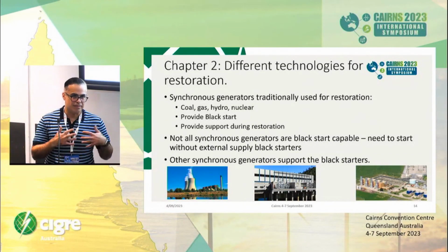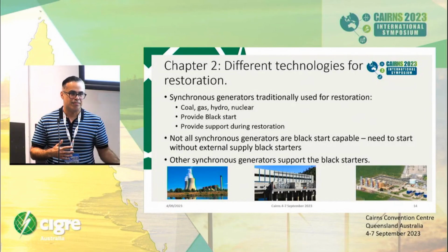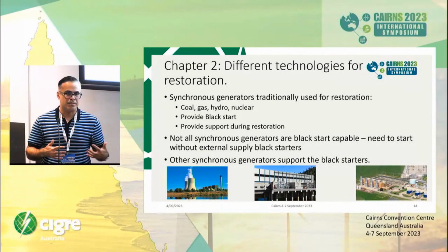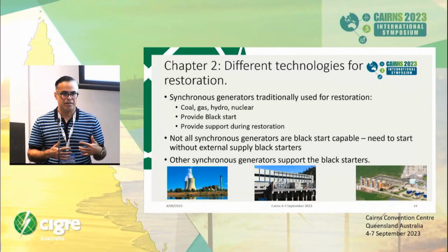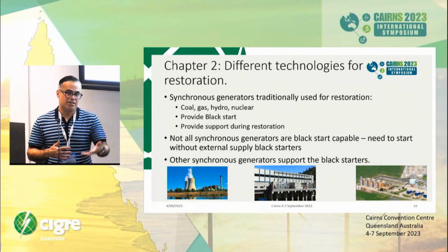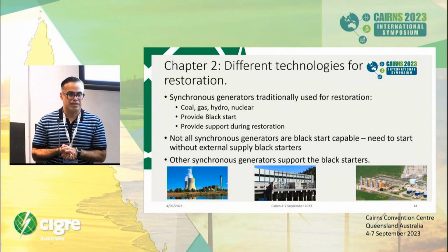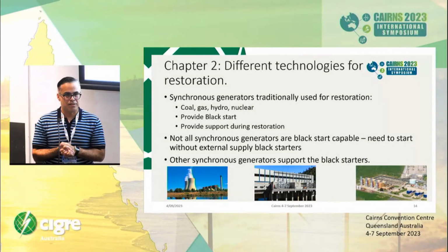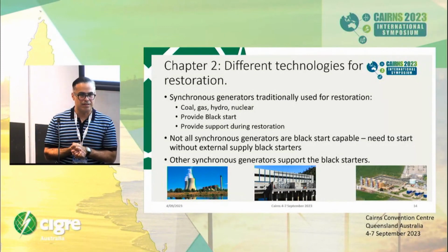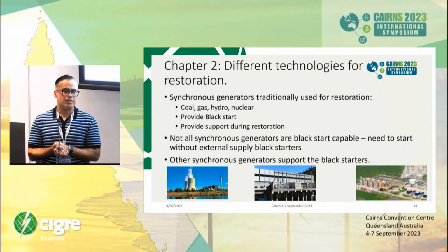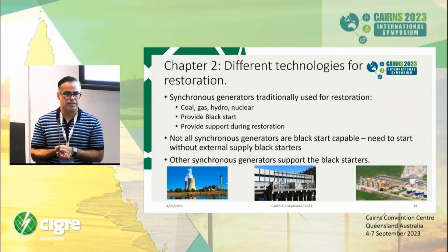I think I made myself clear that this is a system to be restarted. If we can restart a generator 100 times, but it cannot restart the next generator, or like you mentioned, because the transformer to be energized is too large, but it could have been soft started, these haven't been understood and not reflected in the restoration plan.